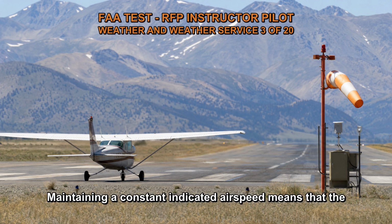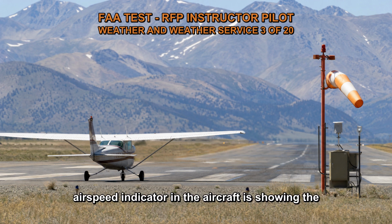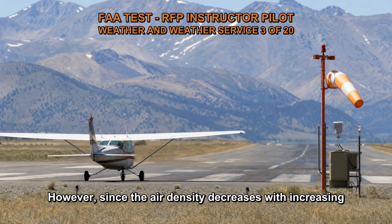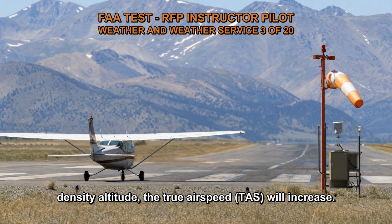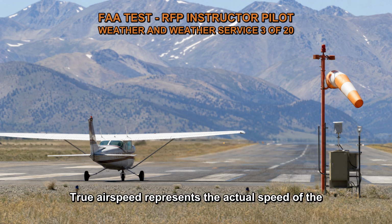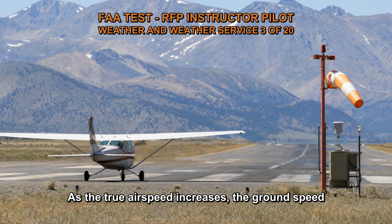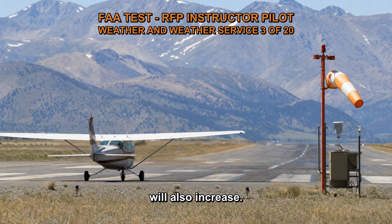Maintaining a constant indicated airspeed means that the airspeed indicator in the aircraft is showing the same value. However, since the air density decreases with increasing density altitude, the true airspeed, TAS, will increase. True airspeed represents the actual speed of the aircraft through the air and is influenced by air density. As the true airspeed increases, the ground speed will also increase.